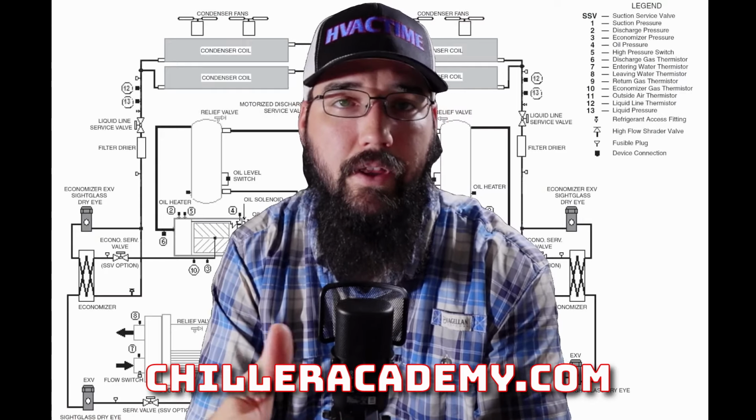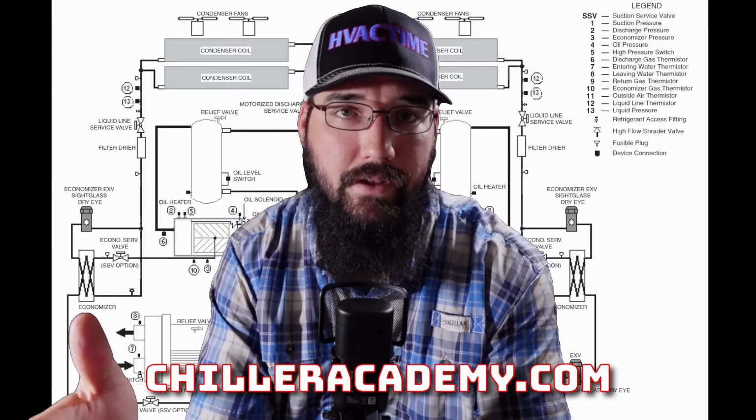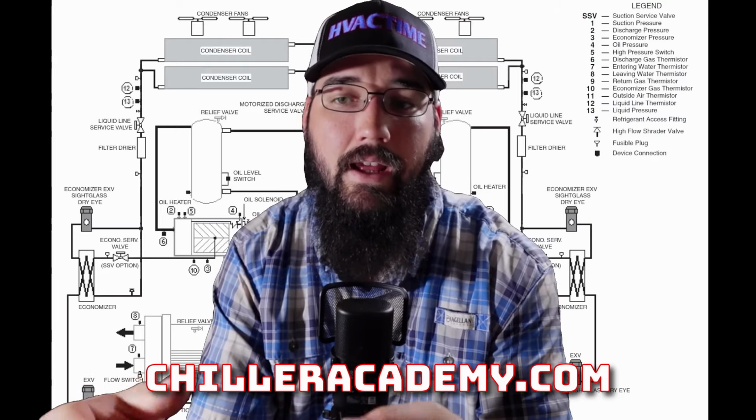That's where current limit comes into play. Then as the load comes down, as our refrigerant settles out and our conditions lower, even though our slide may not have moved, or we may not have sped the compressor up, our current draw will begin to fall.